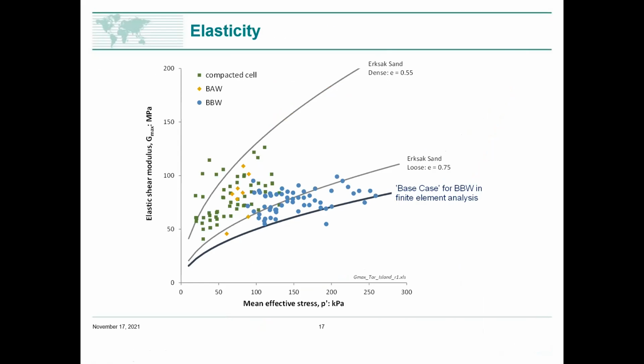Now, elasticity. We have scads and scads of Gmax data in situ. As I'm sure many of you are aware, the seismic cone has almost become the weapon of choice for our site investigations. And it's virtually free data. And this is a bunch of data. This is actually from Suncor, from the Tar Island site.